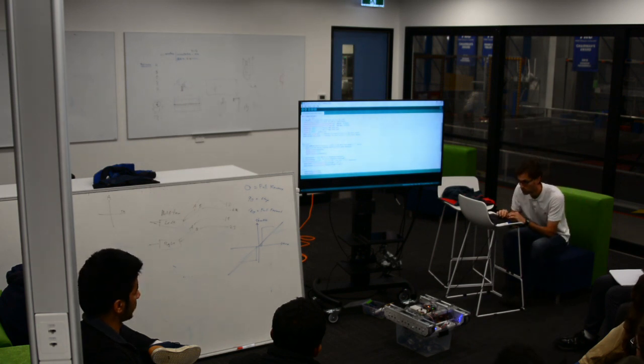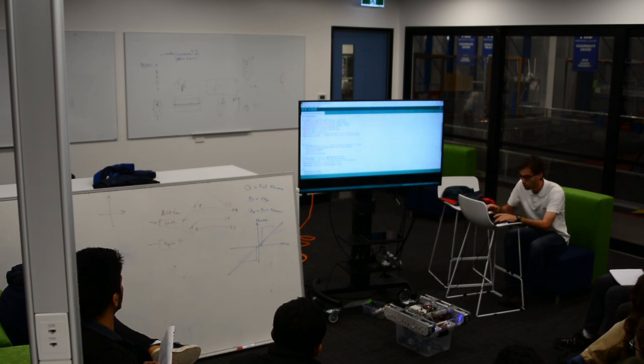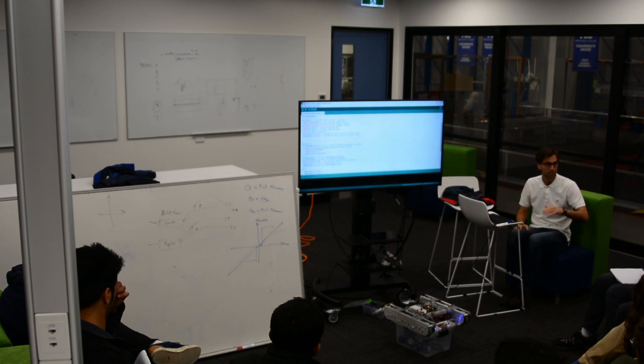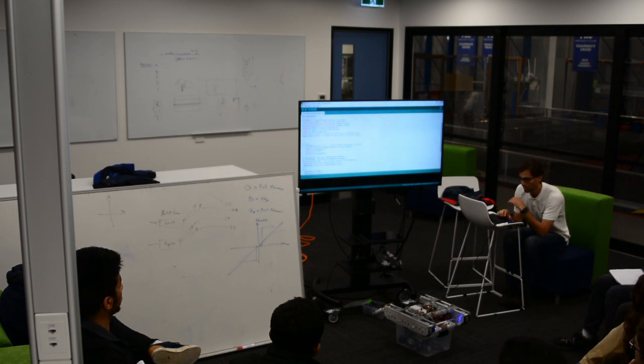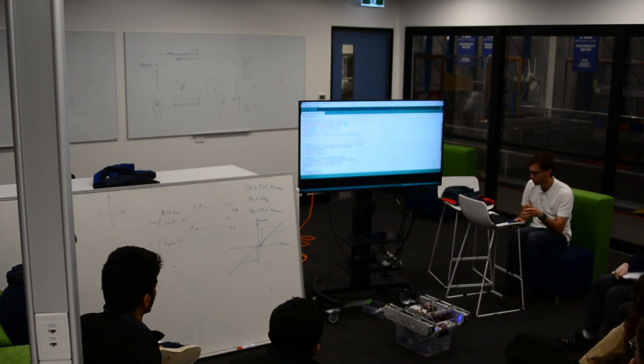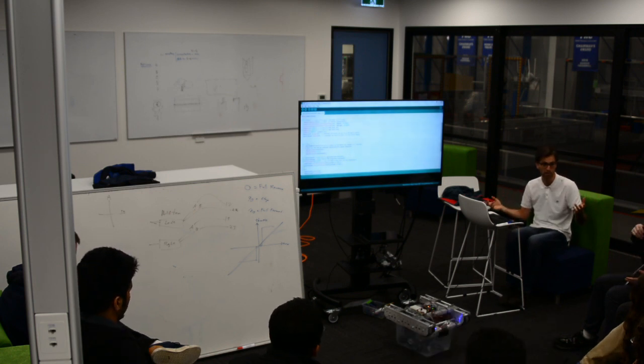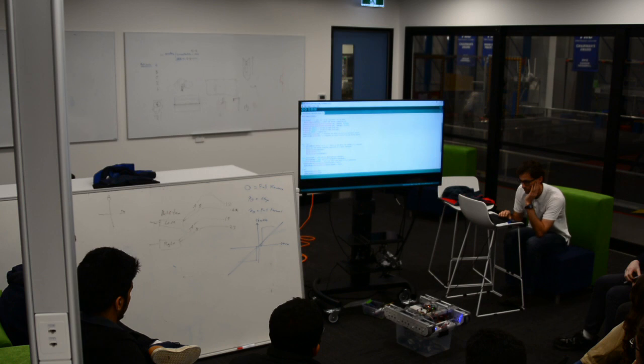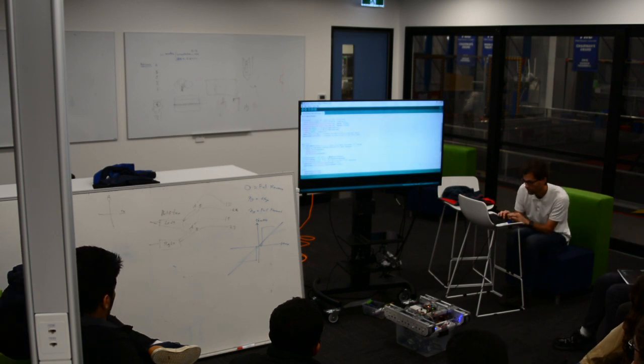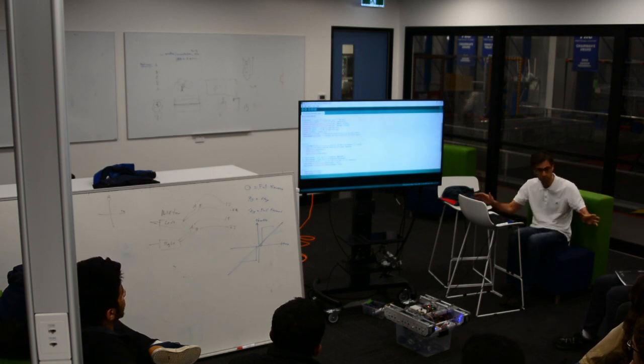Let's turn that way down for now because initially when you set up a proportional system, start with your proportional gain being really low, and then you slowly increase it until it starts to behave well, then you increase it more until it behaves badly, then you back off a little, okay? And now what I found with all this float math was that it worked great at low numbers, and then as I increased it at about 0.5, the whole thing went haywire, and you dig through and you dig through and you figure it out. I don't know for sure exactly why, but I eventually fixed it.